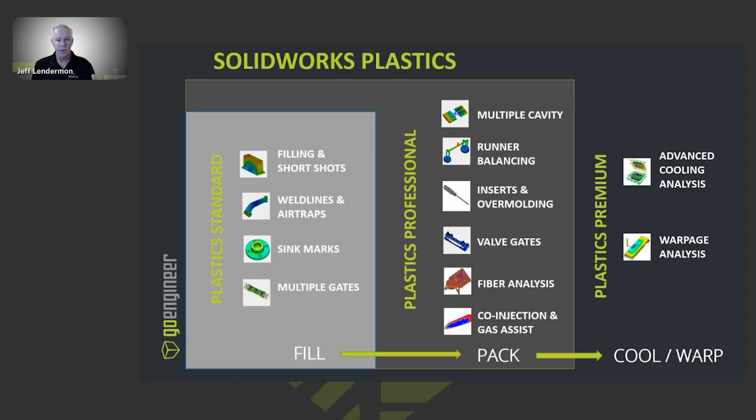And then Plastics Premium, so that's our highest level. We get everything from Standard and Pro, but it includes the cooling analysis and also your warp analysis. The advanced cooling is going to actually run a CFD analysis on your cooling channels, which I'll go pretty deep into today. And then we'll also look at part warpage. That's really one of the things I'm going to concentrate on for the part that we're looking at, the warp analysis.